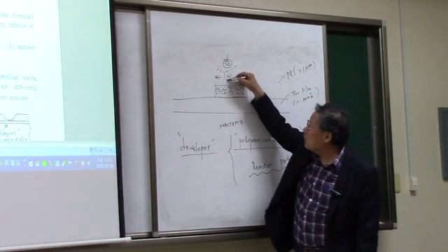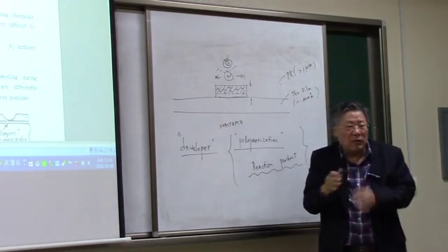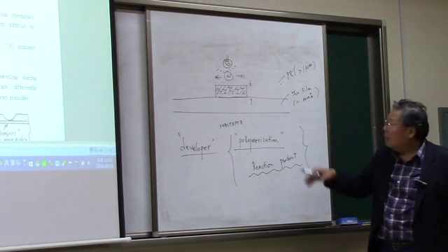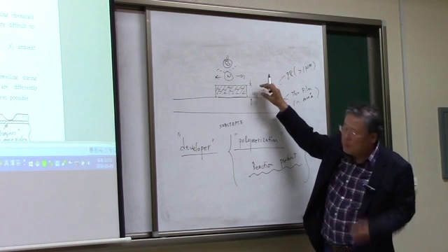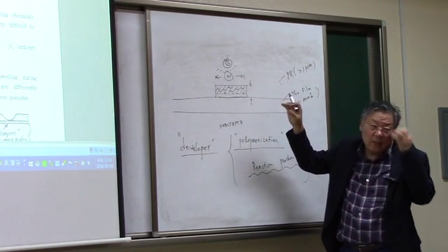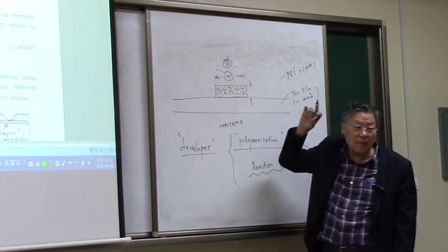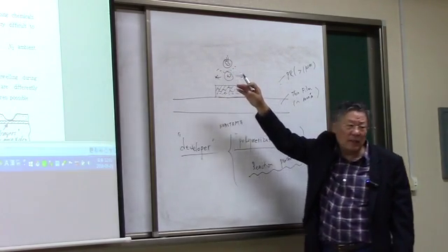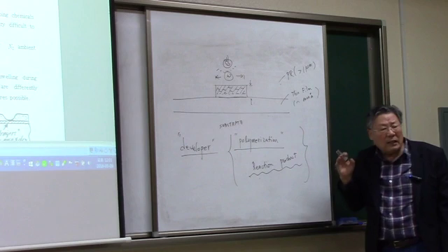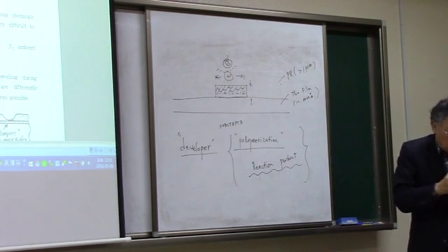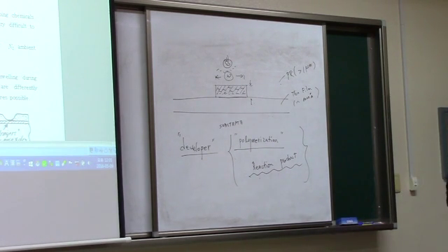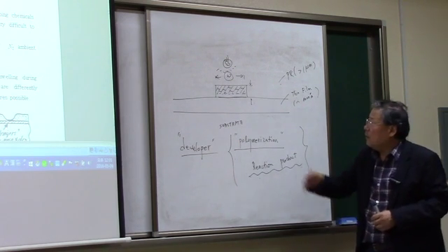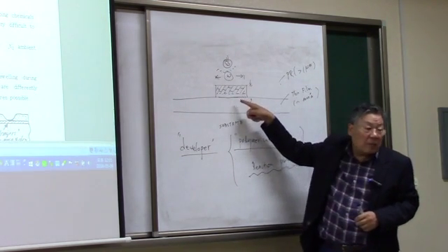And that is depending on the width. If it is too narrow, then the light is not going to penetrate enough. And if the PR thickness is thick, the same thing happens, okay? And if the light intensity is not enough, in other words, if you set too short an exposure time, then this thing will happen, okay?